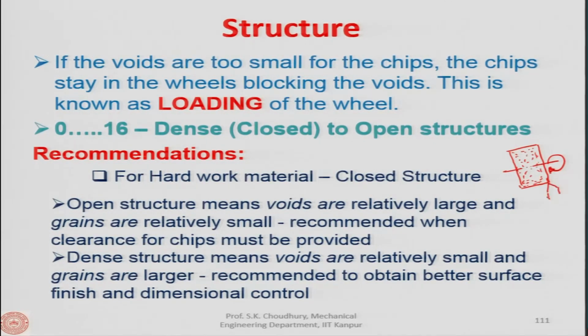Now, here this is a diamond pin, and that diamond pin is used to remove the surface layer from the grinding wheel. Here it is given the feed like this, and it reciprocates. This process, as many of you will know, is called wheel dressing.